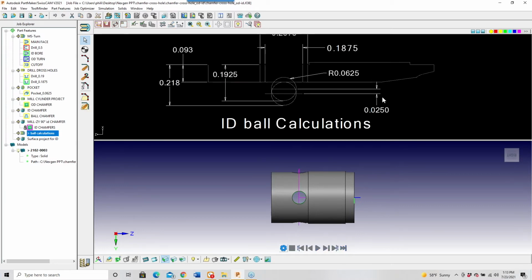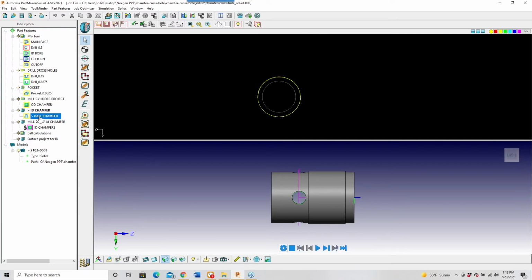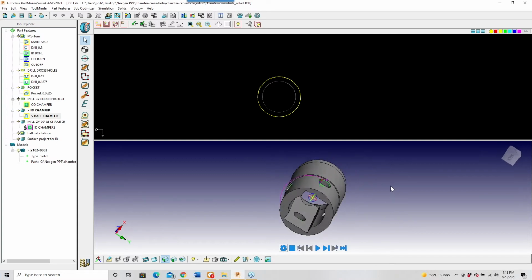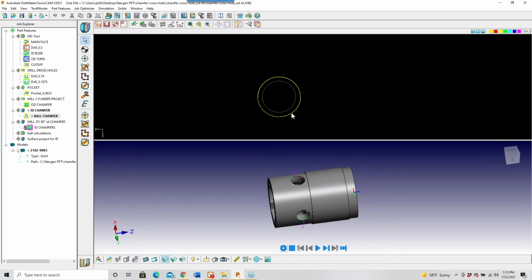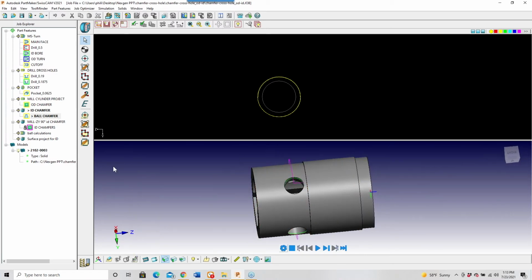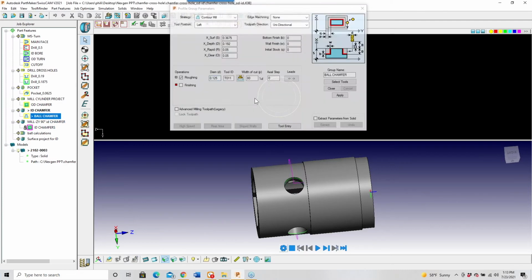What I'm doing here is I'm determining what the depth of the tool should be. And then in the chamfer method itself, I'm offsetting the hole diameter by a value that will allow me to use the upper edge of the lollipop cutter to cut this bottom edge, but not have the offset so far that the shank is going to rub onto that surface right there. Okay, so let's take a look at the tool.